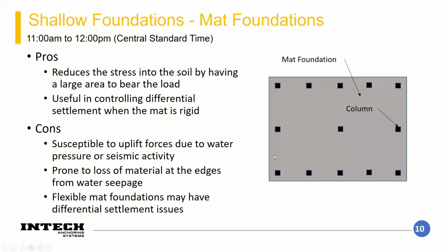Whenever you've got a foundation this large, it's going to require a lot of reinforcement to be a rigid foundation. And if you don't achieve closer to that rigid condition, that's when you open the door to this thing still having differential settlement issues, even though on paper it's a good way to mitigate it. If you're not designing it as a rigid mat, then you can still run into those differential settlement issues.